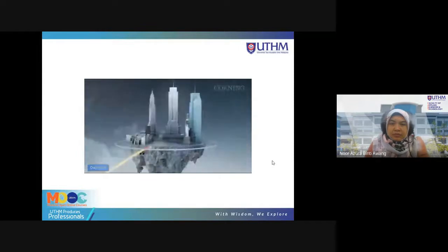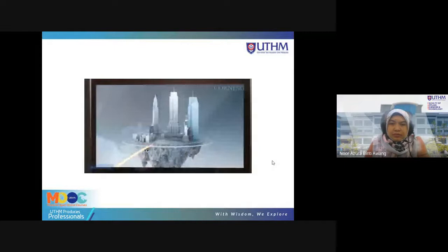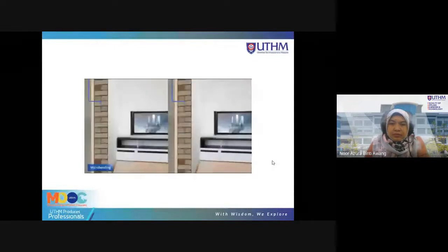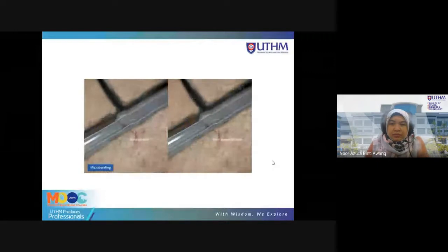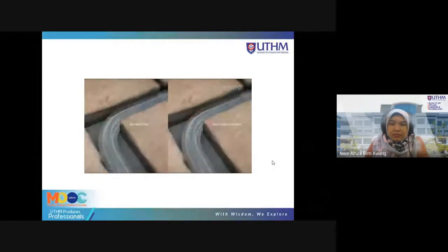Macrobending and microbending are optical effects that occur when the fiber is bent from a straight axis. Microbending is an attenuation increase caused by high-frequency, small-radius bends along the length of the fiber. Macrobending is the attenuation associated with bending or wrapping the fiber. Both of these conditions can allow light to leak out of the fiber, meaning some of the original signal is lost. Using a bend-insensitive fiber like Corning ClearCurve single-mode or multi-mode fiber will greatly reduce the loss caused by macrobending.